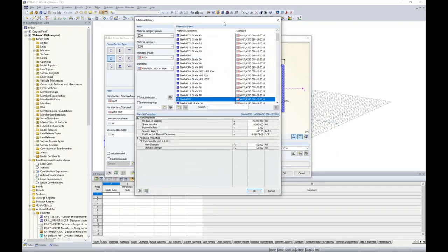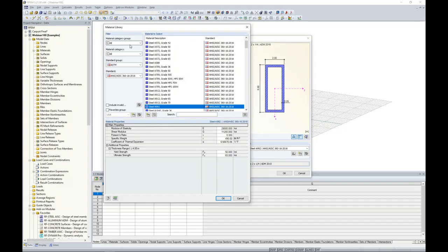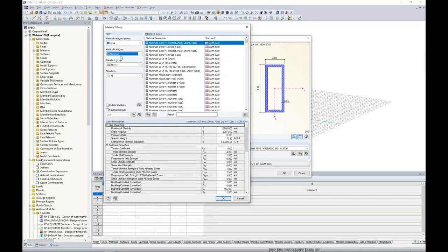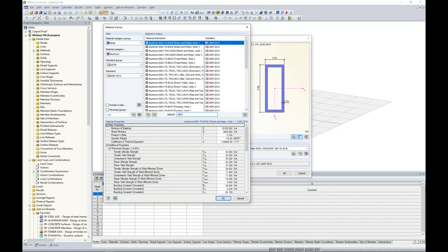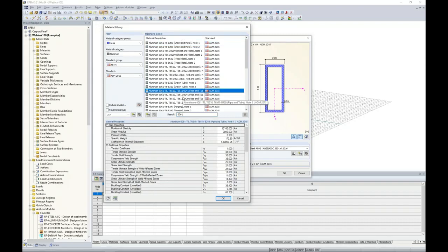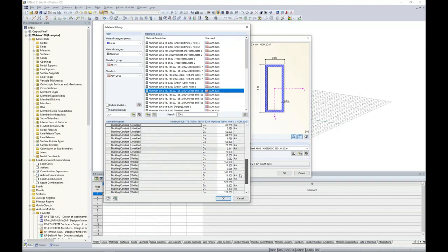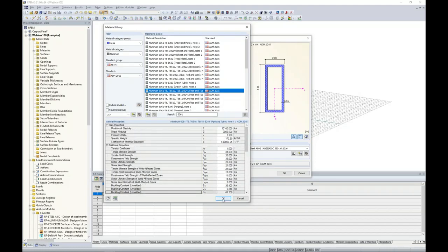Well, that's quite easy by launching our material database, and this should look very familiar. It's almost exactly like what we saw within Shape Thin. We can use our filters over on the left to filter to metal, aluminum, ASTM, and the 2015. Once again, I can type in 6061 and I can select 6061-T6 from my list here for pipes and tubes. All of my material properties are presented in this table.